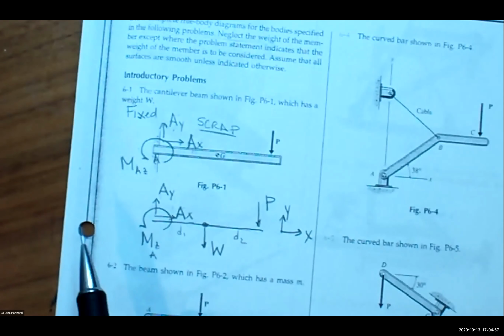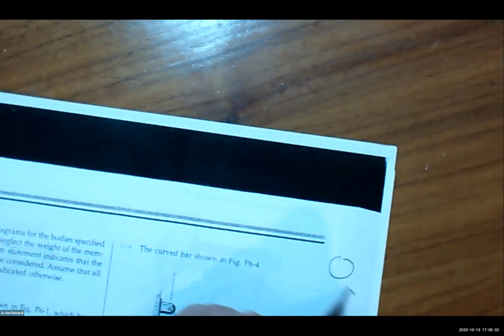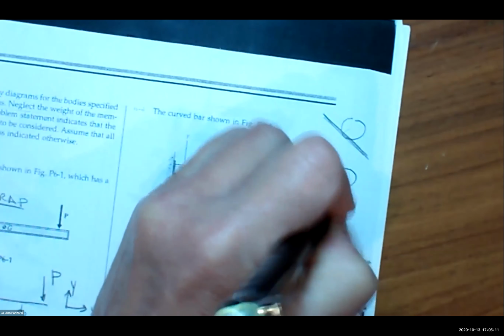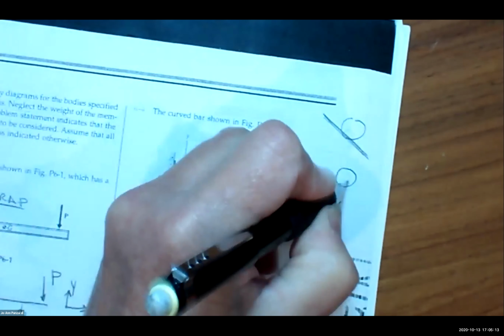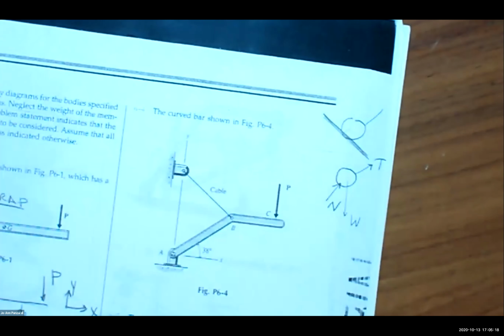Okay, Joanne, I just want to clarify. So basically, in this free body diagram, those are the forces from the connection on the beam, right? That's correct. Remember when we had a cylinder on a surface? We knew there was a normal between here. When we separated the cylinder from the surface, we had to account for that. We had to put the normal in. We had a weight in. And if there was a tension, when we cut the tension, we put T for tension.